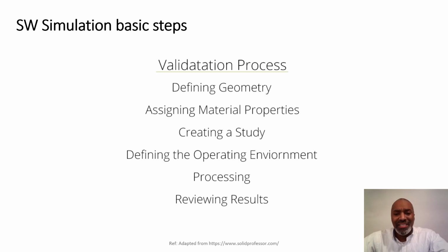If we're doing something that's time dependent, then we're going to need viscoelastic properties or viscous properties. Like, how does this thing flow over time? Does the rate of loading impact how fast it deforms? Does it have any sort of stress hardening or strain hardening? So those things can all be built in.